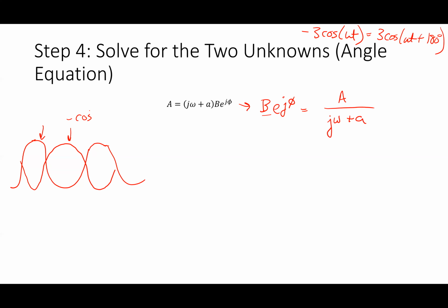So they're shifted 180 degrees from each other. But the amplitude is still 3. Amplitude is always a positive number. So I don't want to get too confused in that right now. That wasn't what I want to talk about. But what always screws people up is when you have a negative real number, that negative is not part of the magnitude. That negative is an angle.